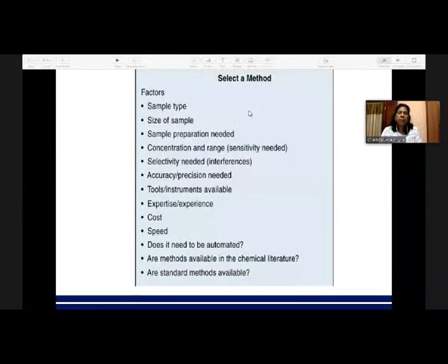In such a situation, you have to use the moisture meter. In the case of the moisture meter, you just put the sample and switch on the instrument, and it will give you roughly, not the exact moisture content, but you can get some idea about the moisture content by that. Accordingly, you can give that information to the production section. Then the production section follows the rest of the process, right? Or to get the product out.